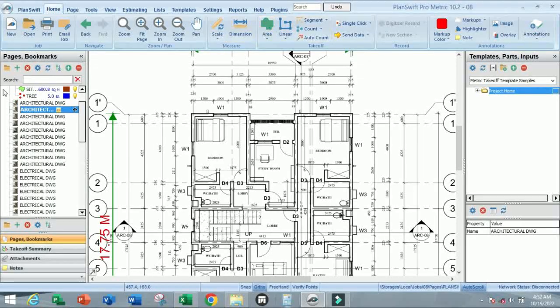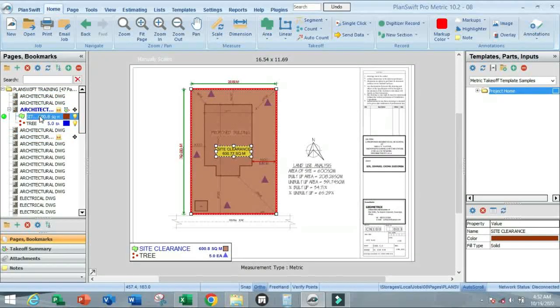So block wall, and let me re-explain this one. This area you can use to take off for square meter and cubic meter. Cubic meter like concrete work, filling, as in laterite filling, hardcore filling, and other items of work that involve cubic meter. Same thing applicable to square meter like DPM, form work, and others.